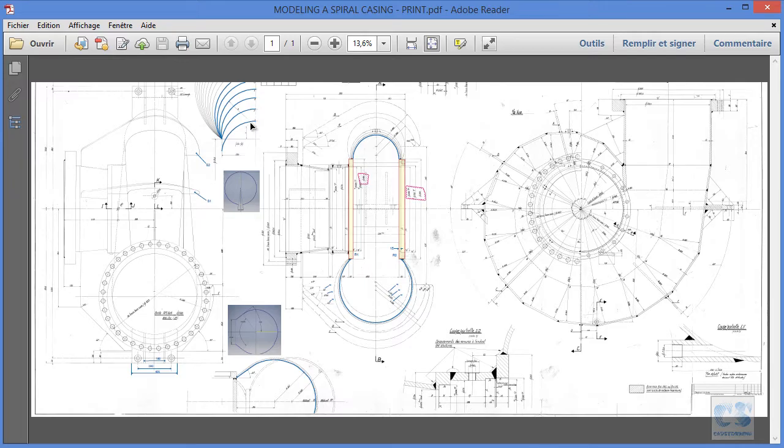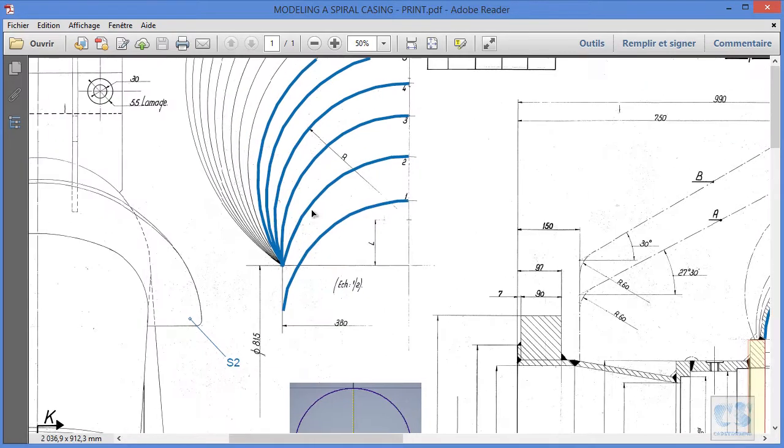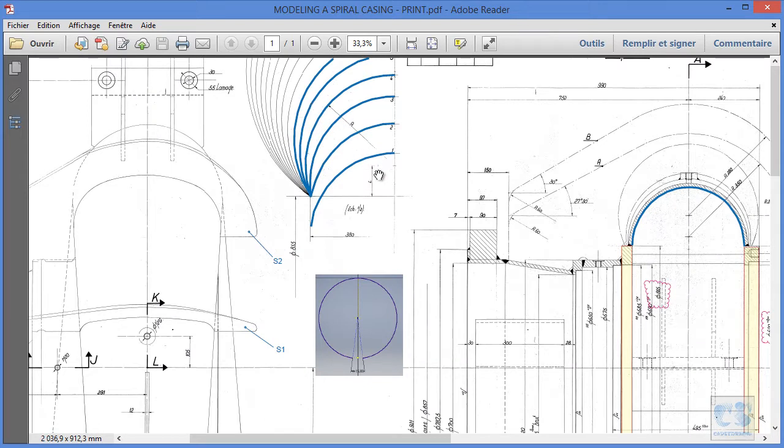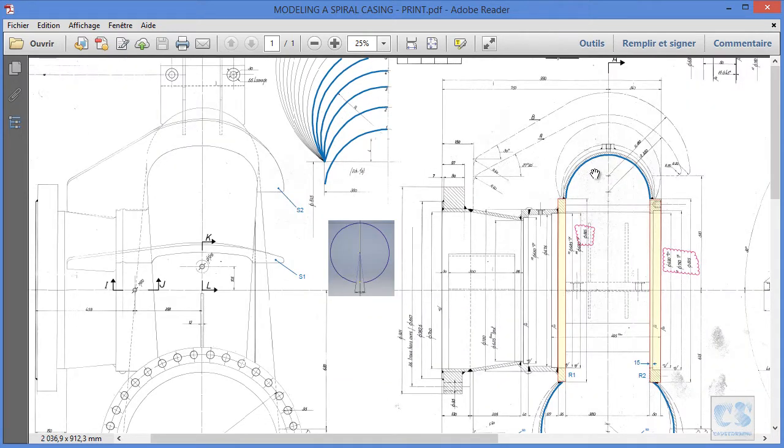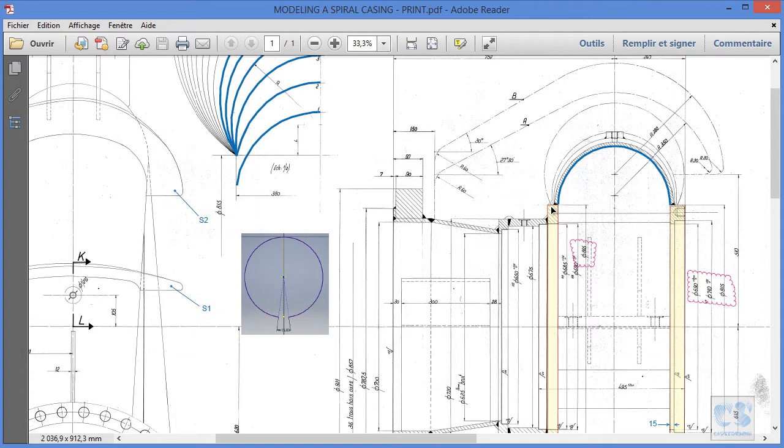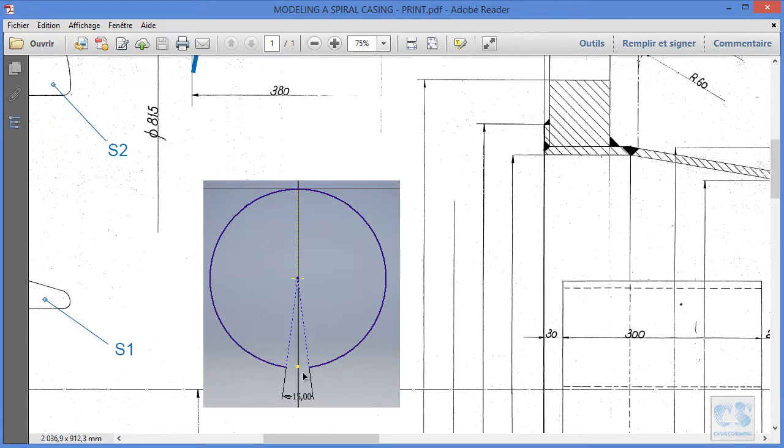The cross-section curves are depicted here. As you can see, there is nothing fancy, just a bunch of arcs with increasing radius. But since the sheet metal components we will create from these cross-section curves will be later trimmed to make room for these two rings where they will be fitted and welded, we will have to draw them slightly oversized so that we are sure to always have enough room for the rings.